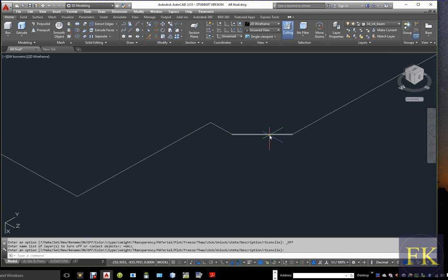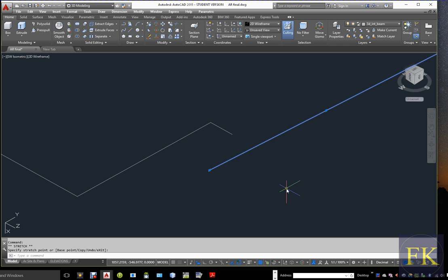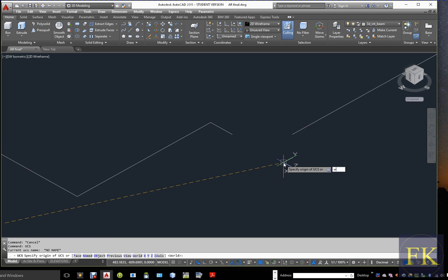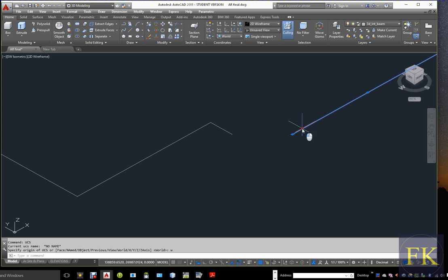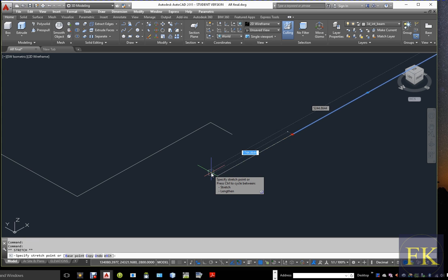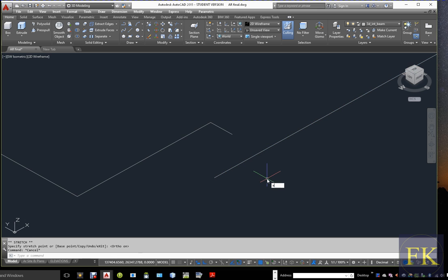The first thing I said is this is no longer chamfer in the upper floor. Okay, let me go ahead and turn my UCS to world, and then I'm gonna pick this here, extend, and then trim.